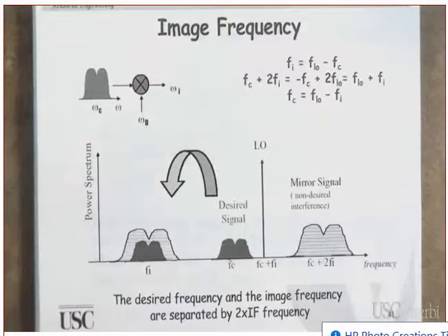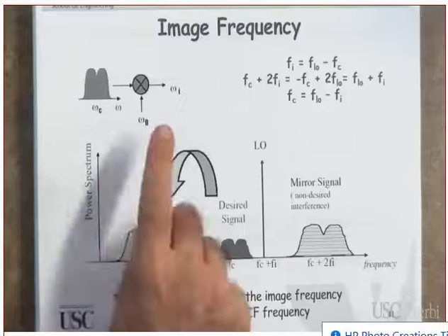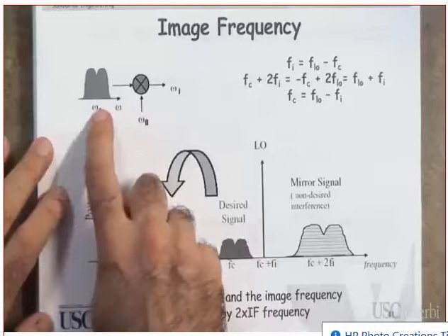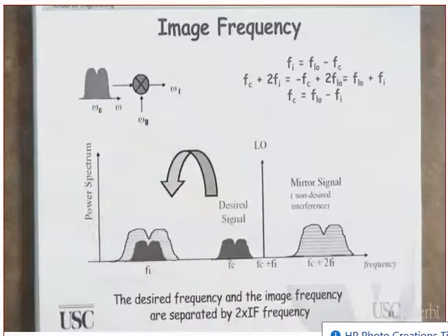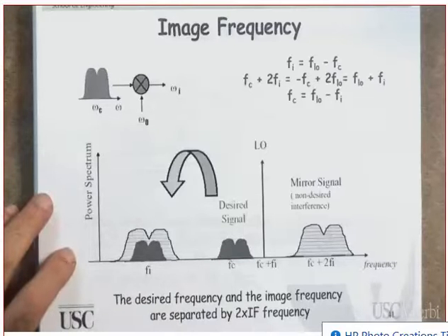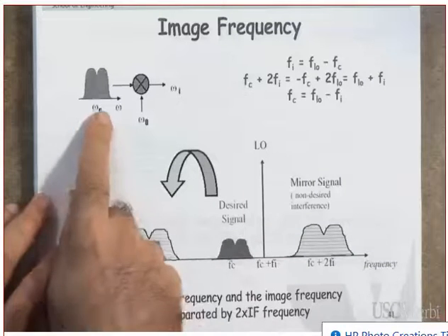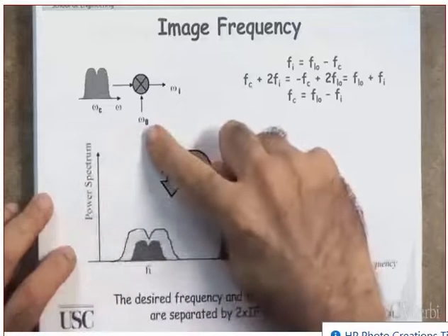Yes. For example, have you heard about double sideband suppressed carrier? What does that mean? You are not going to send a carrier component. So the spectrum will be centered around omega C. But when you talk about AM, AM means it's double sideband, but there is also a carrier component in it, omega C. This is omega naught. Clear?